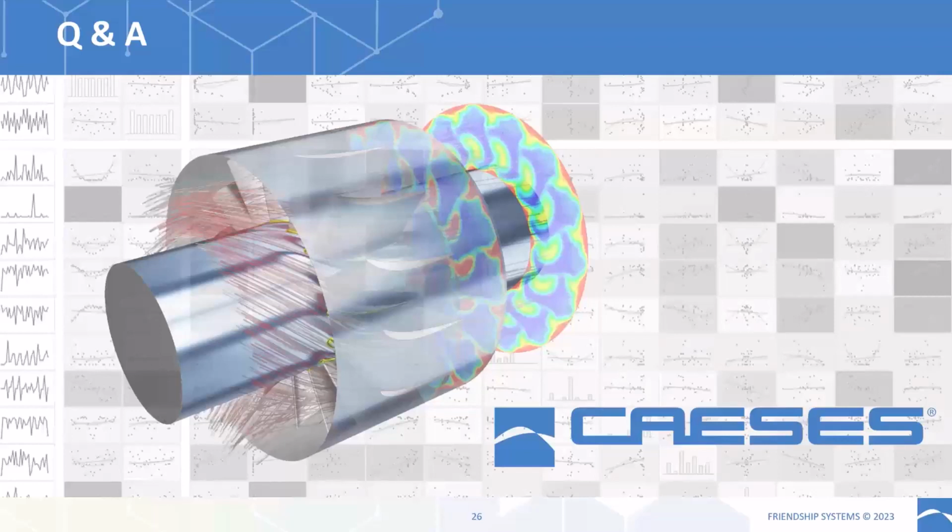That's also possible. Yeah, that's a good point, Carsten. We mentioned that the airfoil blade is mostly used for axial blades, and the camber thickness-based approach is mostly used for radial or centrifugal blades, but it's not a hard limitation. You can use those approaches also for other kinds of blades. So that's a good point.